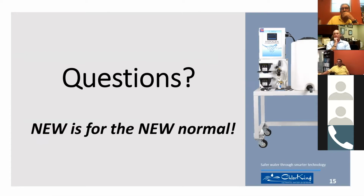So it's just our standard switch mode power supply that we use on our 2.0 and 5.0 MSM models. The system fills up that tank, and it fills all 20 gallons, and the level sensor turns it off. We only turn it on again when it gets back down to just under half, because we want to consistently make high quality product. If we kept topping it up, the product shelf life is about 30 to 40 days, so you've got a good month to use what's in the tank. But if we allow it to drop down halfway, we're consistently adding a good solid 1,000 plus ORP ppm solution in there. So that's why we have it set at those particular levels.